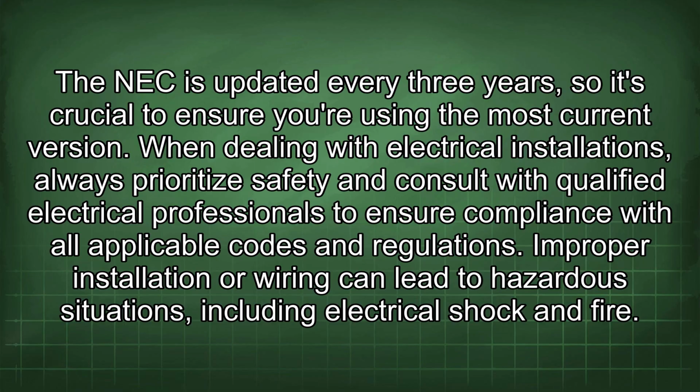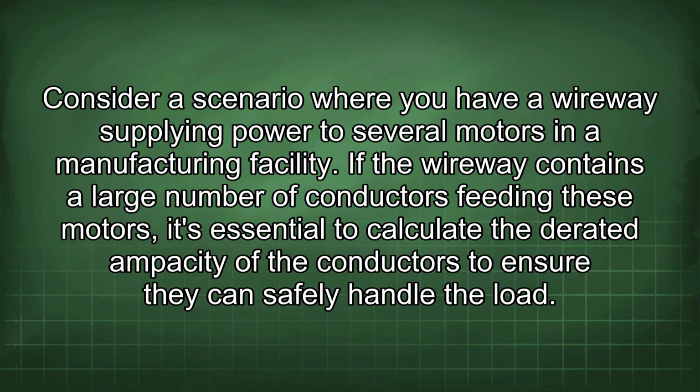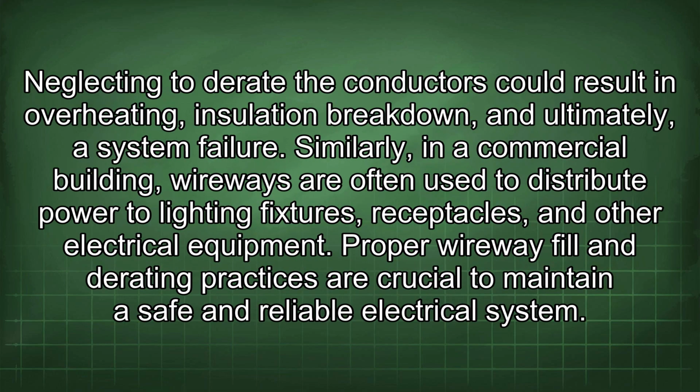codes and regulations. Improper installation or wiring can lead to hazardous situations, including electrical shock and fire. Consider a scenario where you have a wireway supplying power to several motors in a manufacturing facility. If the wireway contains a large number of conductors feeding these motors, it's essential to calculate the derated ampacity of the conductors to ensure they can safely handle the load. Neglecting to derate the conductors could result in overheating, insulation breakdown, and ultimately a system failure.